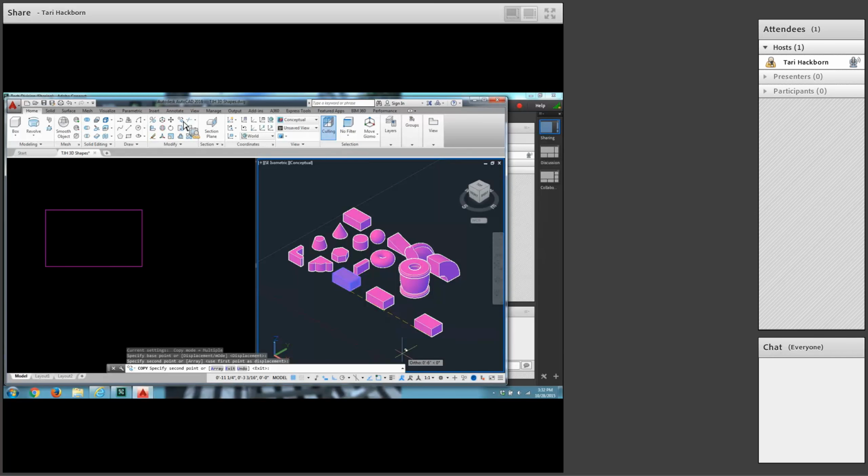You're going to do a chamfer on one of them and a fillet on the other one. The chamfer is more difficult. The fillet works pretty slick. Okay. Whoops, it's still copying. Okay. Chamfer right here, fillet. You are instructed to type D and enter or select distance from the command line. Okay. 3/16 is your distance. Okay, 3/16 and enter. And then enter again for the second distance.